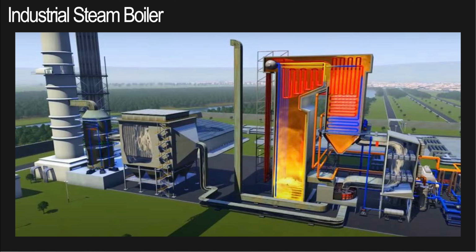Those red things there, those are risers. You see them? So the risers carry saturated steam. The saturated steam is going to be meeting the hot flue gases in the superheaters that you have here, and it will go through 3 different stages of superheat. This is the first superheat, second superheat, and the third superheat. And from there, it's going to the steam header.